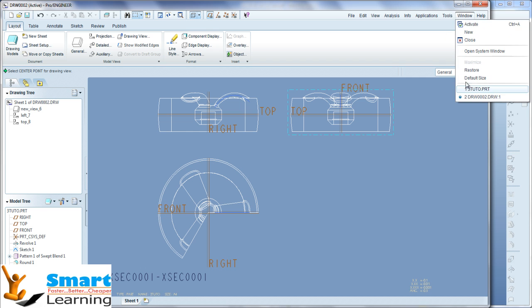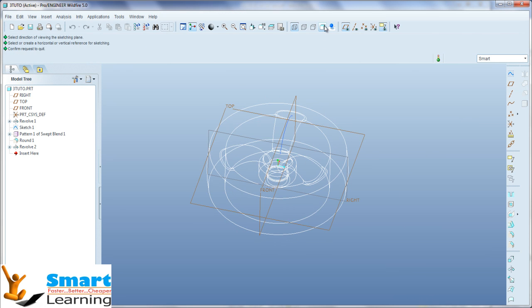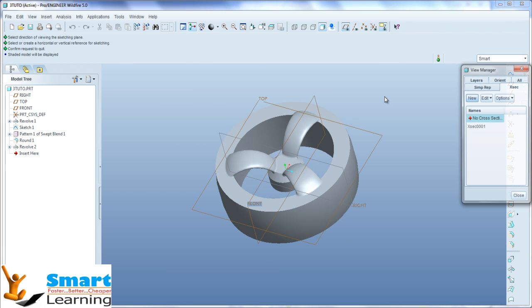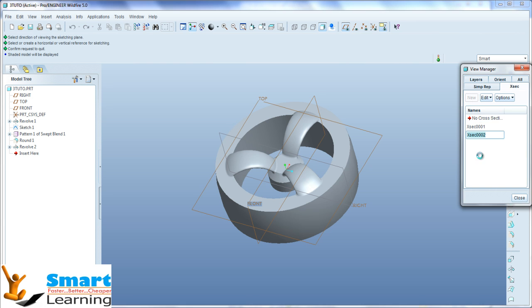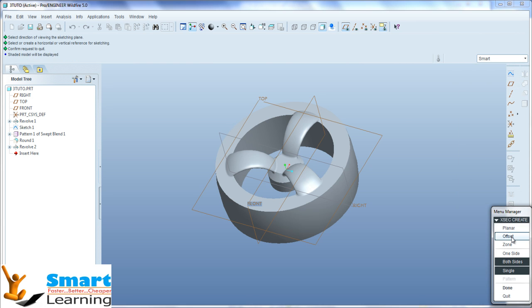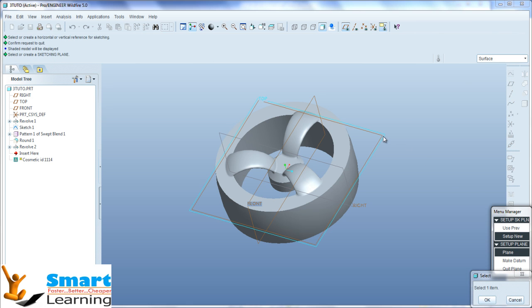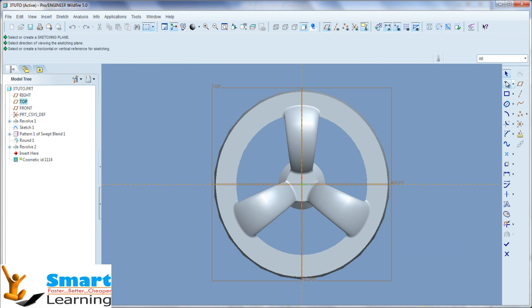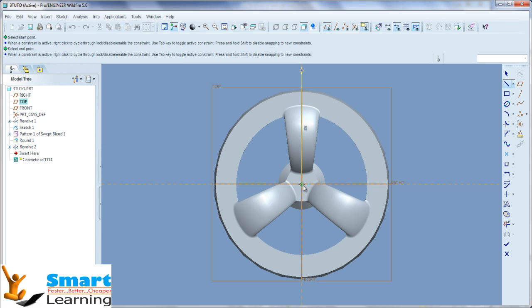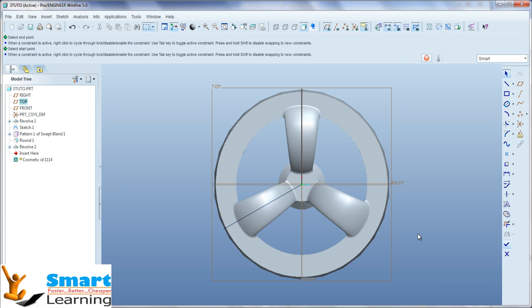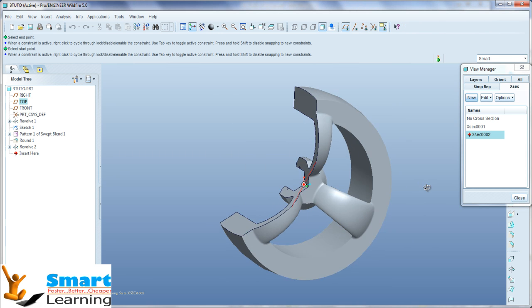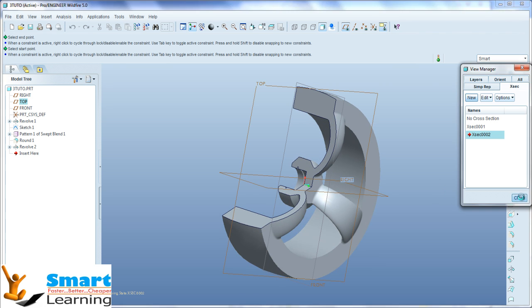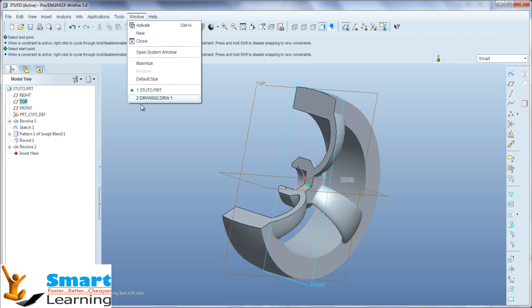This fundamentally starts from the 3D. If you go to the 3D view, here you have the view manager. Inside view manager you have cross section. Once you go to new, a new cross section will be generated. You go to offset, done, you select the required plane, go to OK, default, and here you can draw the cross section which you want to cut. Let us say this I need to cut with the proper angles, whatever angles you need, go for accept, and now if you double click, this section is generated here. This is what we have generated here.